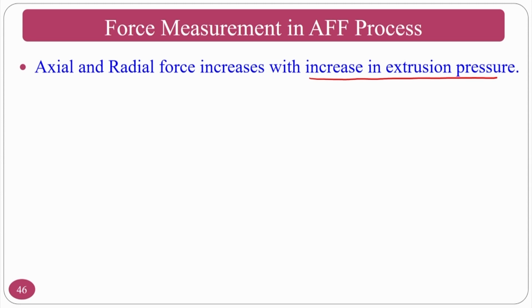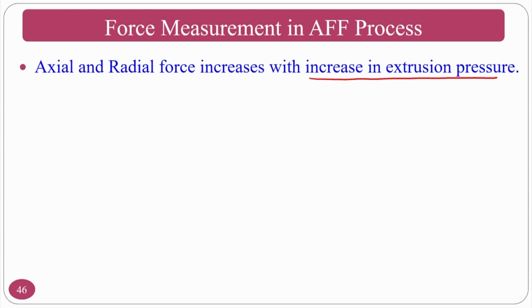Obviously, the pressure exerted on the medium by the hydraulic power pack or the piston will increase. If it is increasing, it is transferred to the workpiece. Why the workpiece? It is the most restricted zone, because the diameter of the workpiece is much smaller compared to your medium cylinder. That is why it is a high pressurized region, which means axial and radial forces are high in that region.